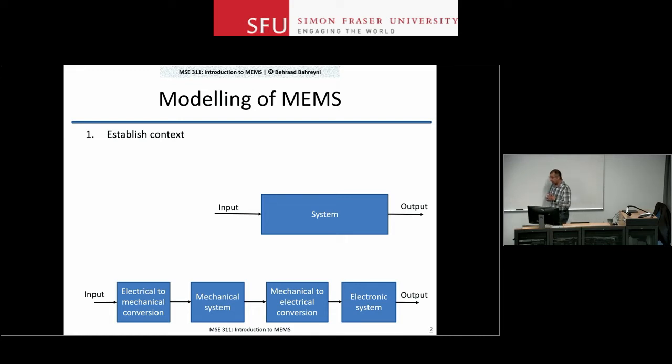So when I'm considering a problem in microsystems, I have to establish context, right? What is it that I want out of this model for this problem? So for example, you may be looking at an accelerometer, and in this case, let's say you want something that is responding to DC signals, fairly low frequency. And we saw from the dynamic analysis before that if you're looking at slow changes, you really don't have to worry about dynamic response, the damping in your system.